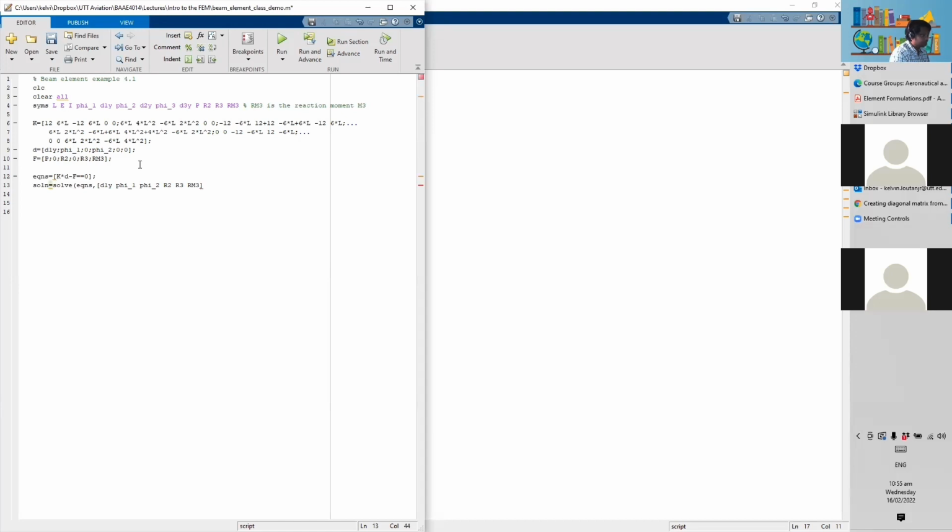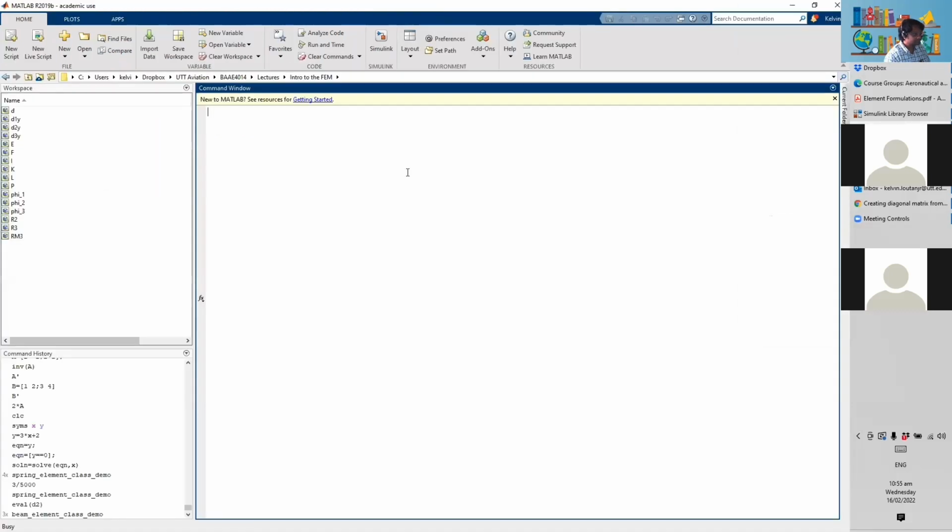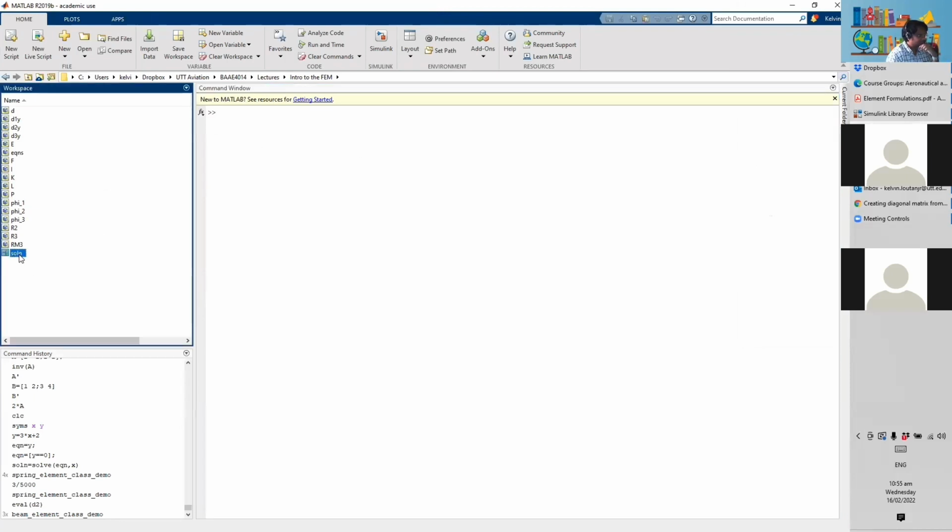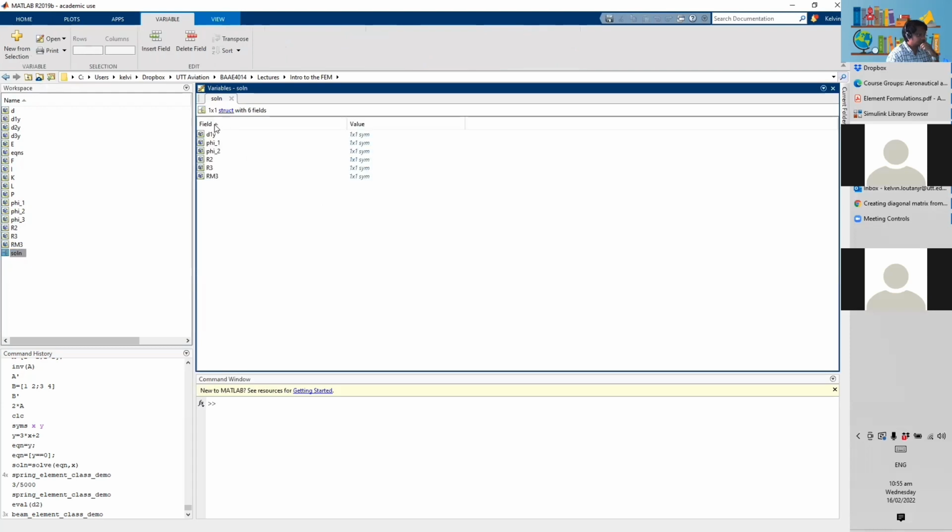And make sure you always close all your brackets, because when you close a bracket, you can actually see what bracket you're closing. So when you close this, you see it close the square. So you can click run now. All right, so done. You see the solution pop up here. Again, this is our solution, and the solution now would be in terms of P. Our moment, of course, will be in terms of P and L.